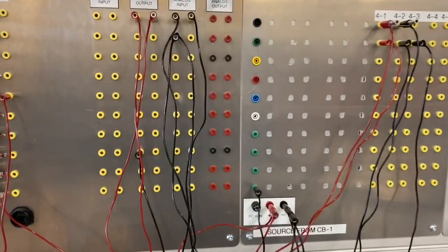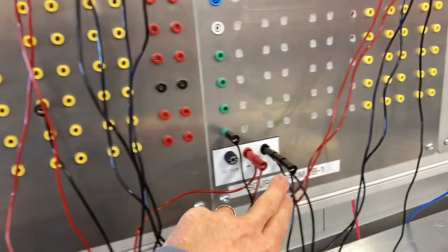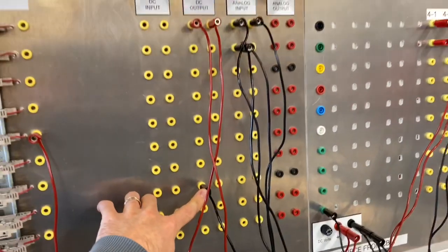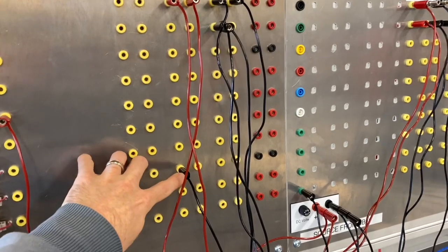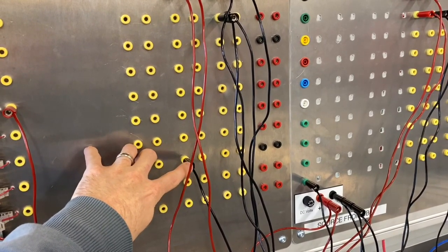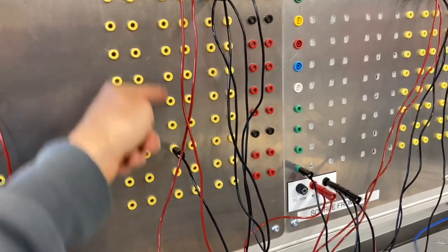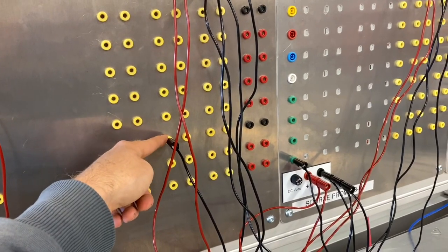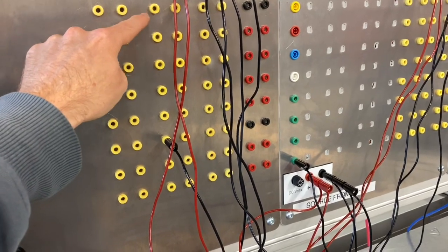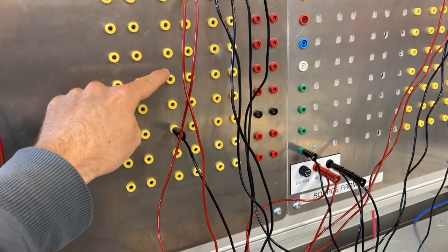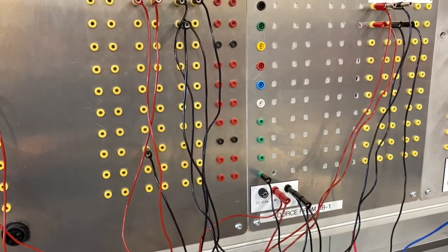One other thing that was critical here that I missed pointing out was this. I had to connect this to the negative of our power supply, this terminal right here. My output wouldn't work properly without this connected. So this will be something that'll get you to look up in the manual, what this terminal is. If we count down 1, 2, 3, 4, 5, 6, 7, 8, it's 8 down from the top left here. It should be an even number, right? So 1, 2, this would be 4, 6, 8, 10, 12, 13. This would be terminal 16 here.